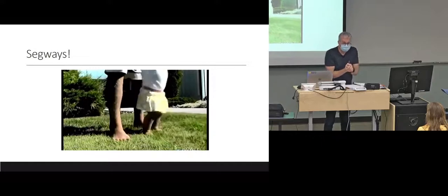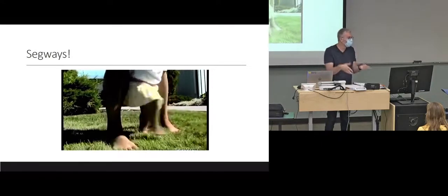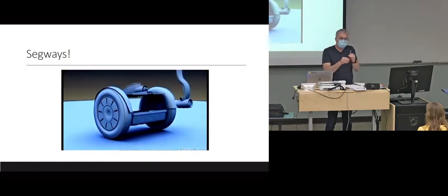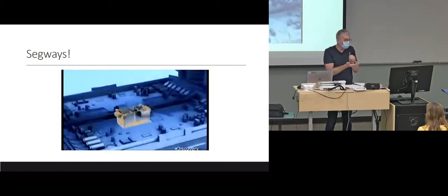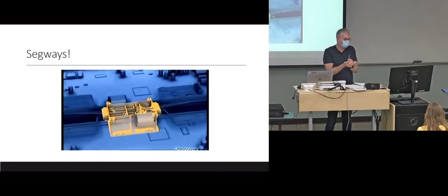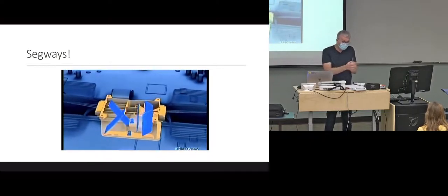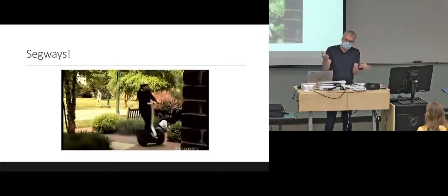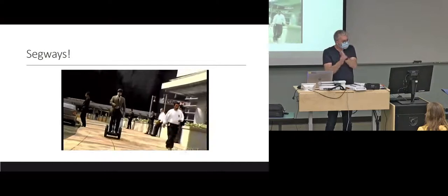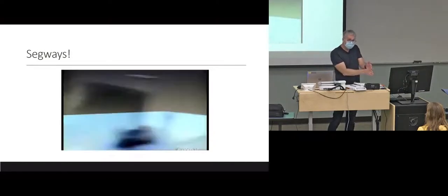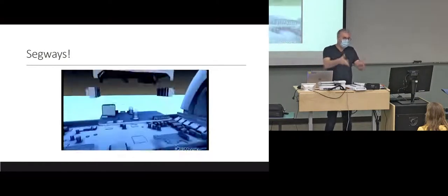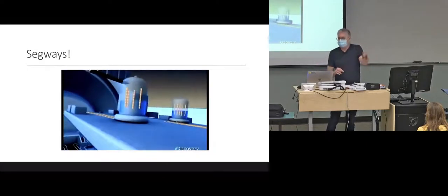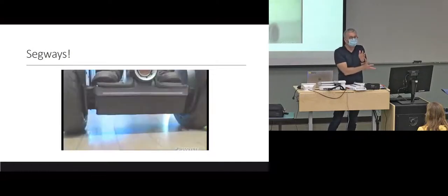That is hard, okay? So this is where the model predictive control comes in. It has a model of how the pendulum interacts with the cart. That's the Segway model. It knows that. You want to get to here, you're going to use least squares control, minimum energy control, to take you from a given position to the goal position. And the model says, if I apply this sequence of controls, what is the effect on the displacement of the pendulum?